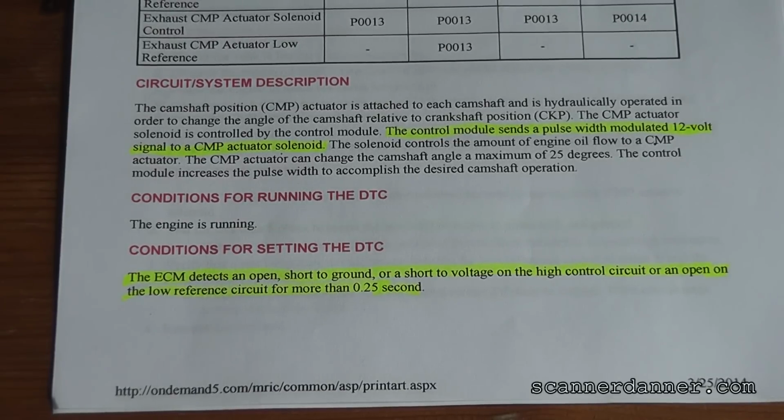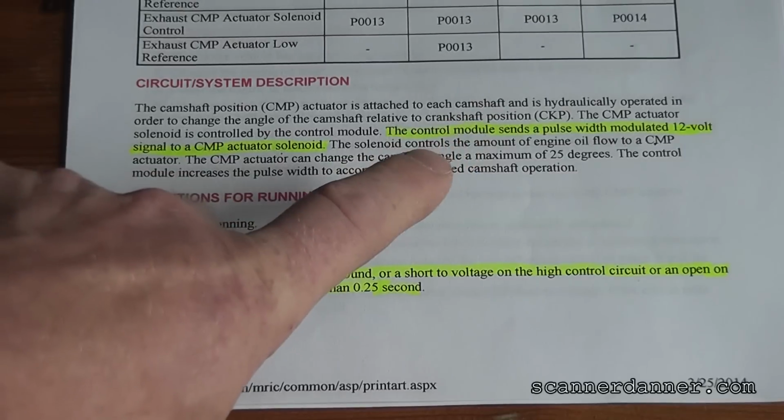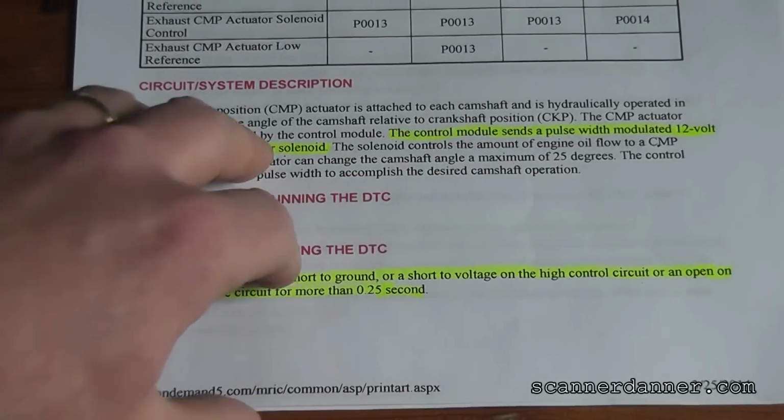So there you go. This is going to be a wiring issue or solenoid issue. Not really too much worried about the hydraulics or any other sensor. This is going to be a trouble code that's just associated around the controls of this solenoid. So this should be a pretty simple job. And again, going into this, it's power side switched according to this. Pulse width modulated, meaning an on-off signal.